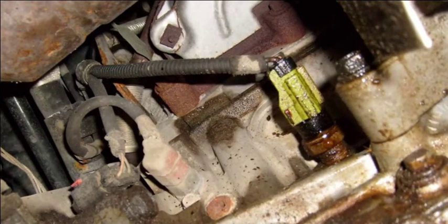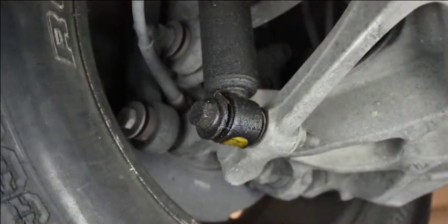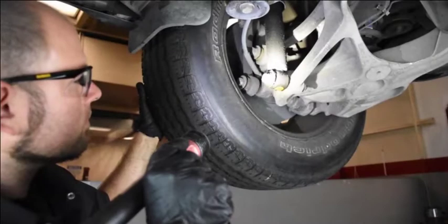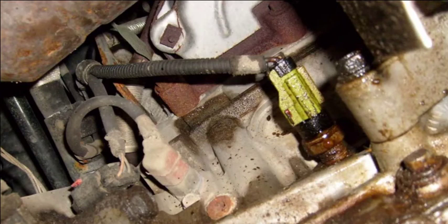An external pressure leak can occur at the oil filter, oil pressure sending unit, oil pump, and where any component that uses oil pressure to operate, like a variable valve timing solenoid. These leaks can quickly deplete engine levels to below normal and lead to severe engine damage and must be corrected quickly. Also, the oil can settle on a variety of components, including air-fuel ratio sensors and suspension components, and damage them. Pressure leaks are usually repaired by replacing the faulty component, like the oil sending unit.